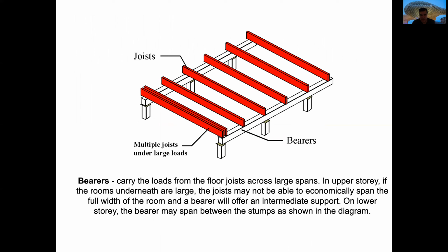In this particular case, because this is a traditional wood system, in order to have a cheaper foundation, it will be more convenient to have foundations that are not deep, but many of them. Therefore, we can see here that the bearer is supporting what seems to be a smaller span, but it's because there are multiple small foundation columns that are supporting it.